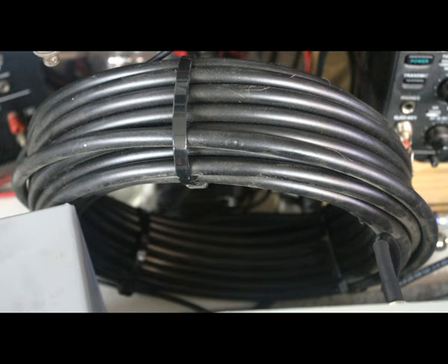This little coil of joy is the LMR 400 coaxial cable. It's just a regular old LMR 400 with UHF connectors on each end, and it connects between these two matching networks. One of the matching networks is going to set the load standing wave ratio, and the other one's going to correct the transmitter, just exactly like you have an antenna tuner in your shack on the table that you use to correct for little problems with your dipole antennas or whatever you're using.